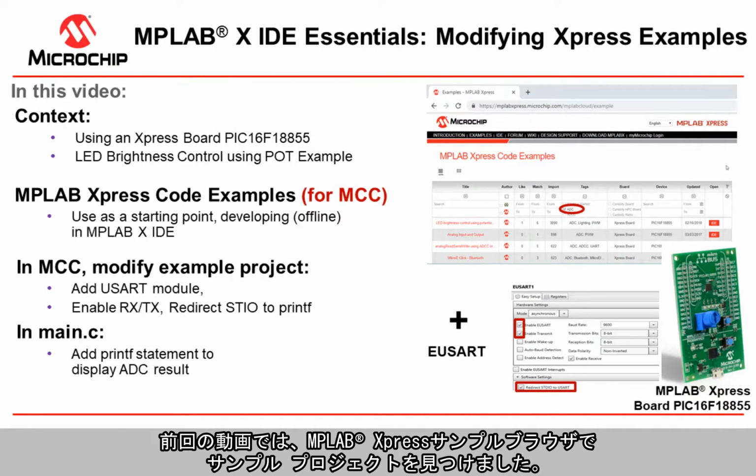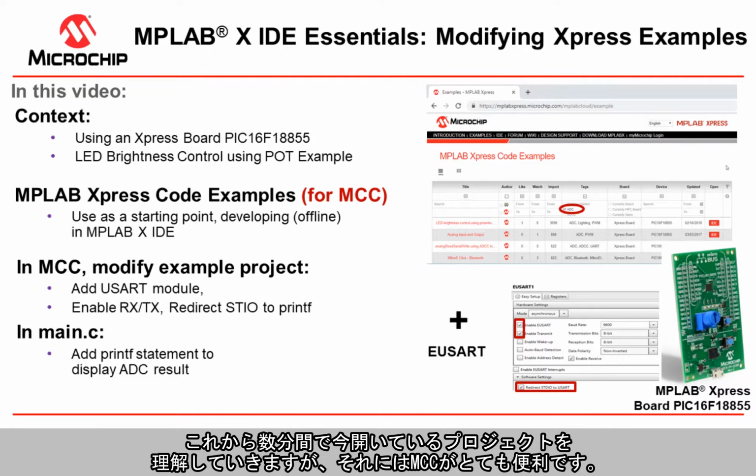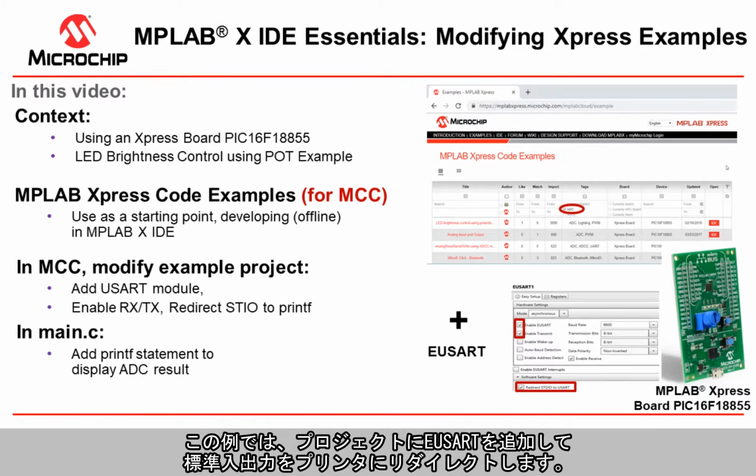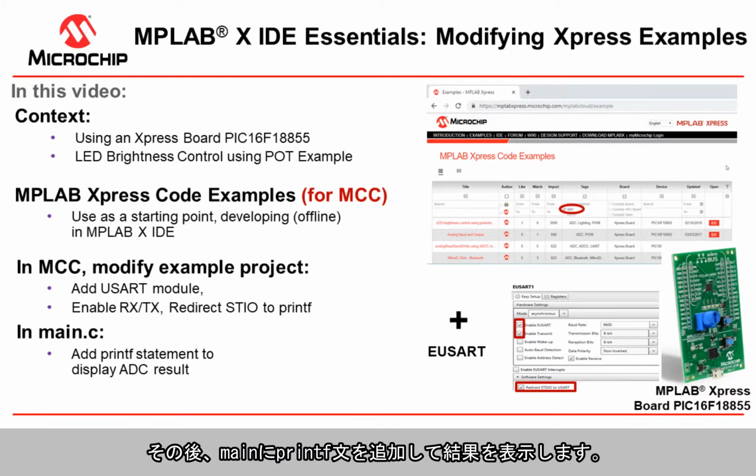In the last video, we found an example project on the MPLAB Xpress example browser. Now we're going to spend a minute understanding the project that we've opened, and MCC can be quite useful for that. We're going to look through the application level code, and then we're going to use MCC to modify the project, in this case adding a UART to it and redirecting standard IO to printf, and then in main we'll add a printf statement to display the result.